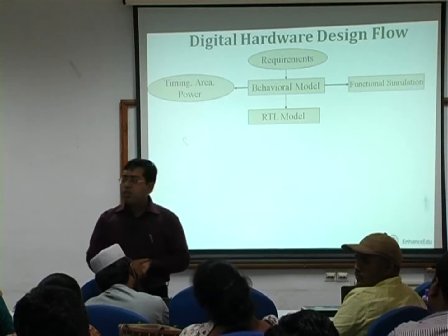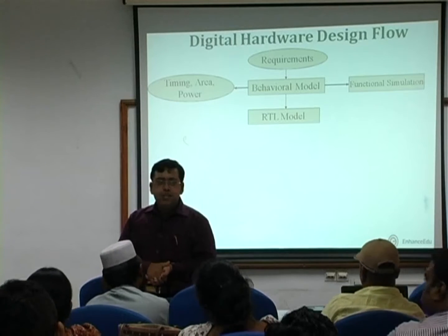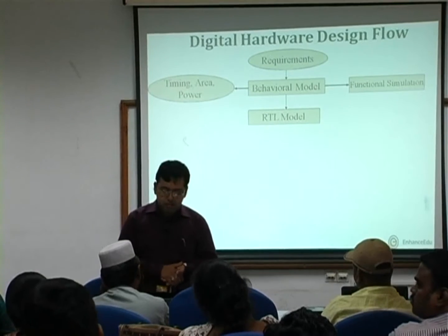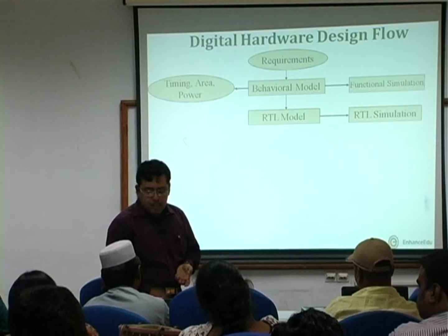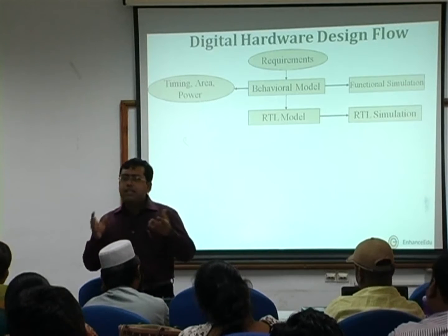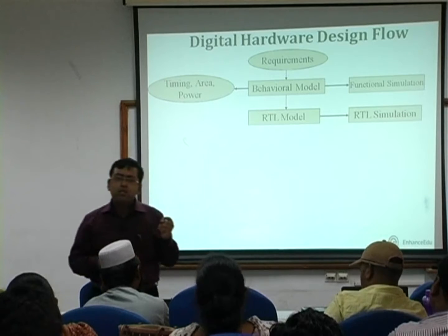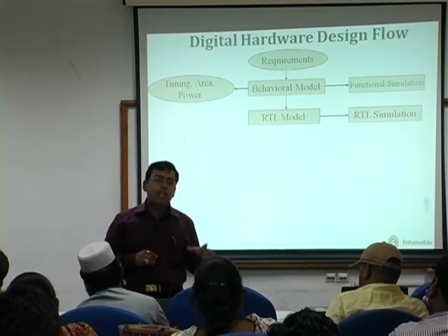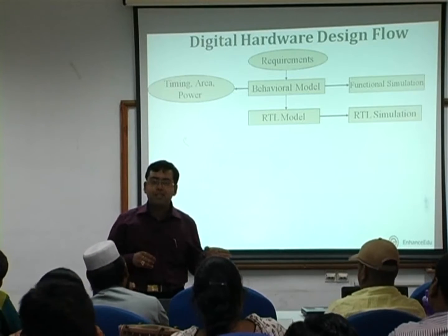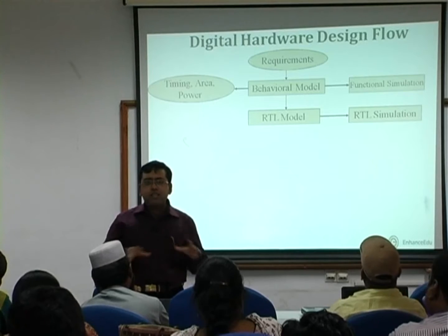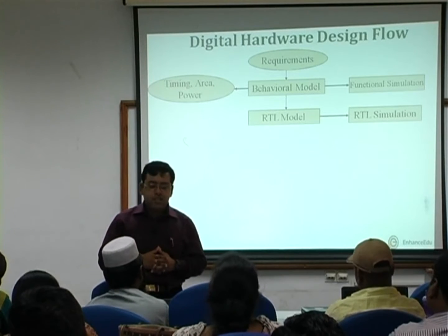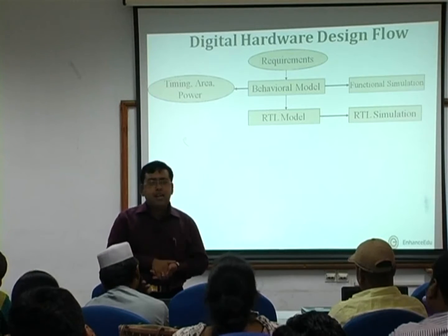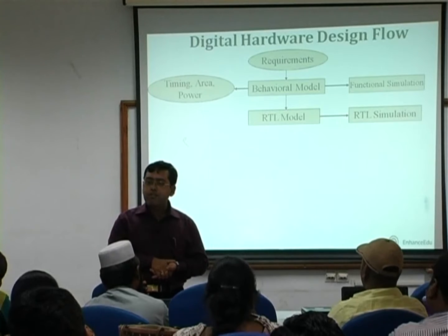Next comes the RTL modeling phase, in which you visualize the circuit as an interconnection of register transfer level components, and then you perform the RTL simulation. These RTL components need not be only registers. It can have other middle level components like multiplexers, decoders, encoders, and so on. All these components we collectively call register transfer level components, and the circuit is visualized as an interconnection of these register transfer level components.